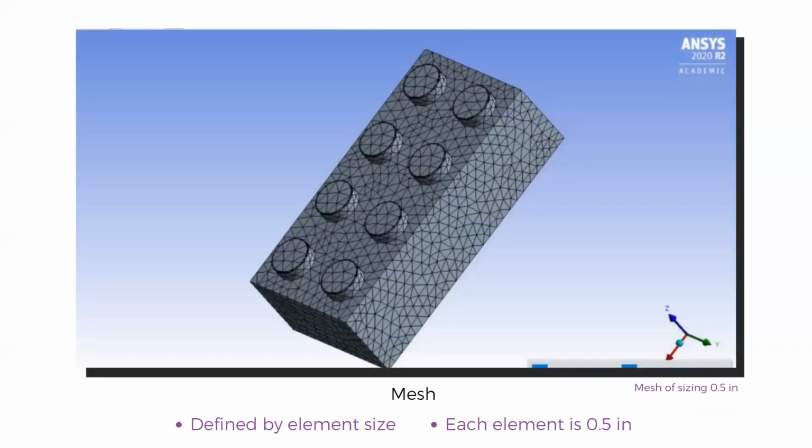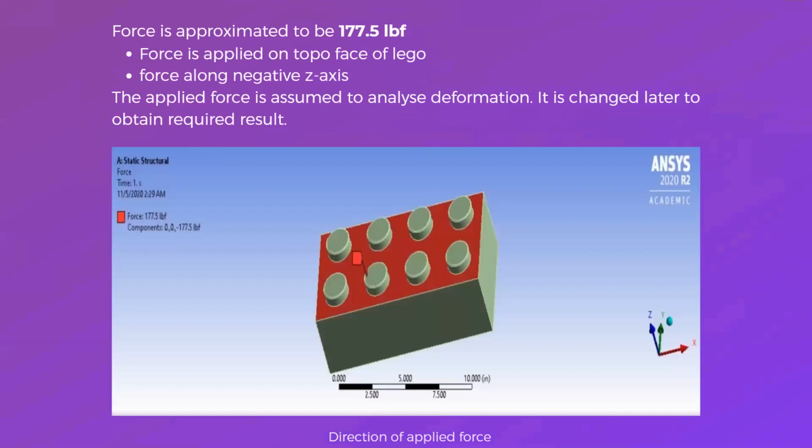so we skipped those. Moving next, we used the maximum possible mesh which was available under the given ANSYS license. We used the element size mesh division. We could have used the spherical division, but since the force being applied was perpendicular to the surface and uniform at any particular position, we went with the element size.